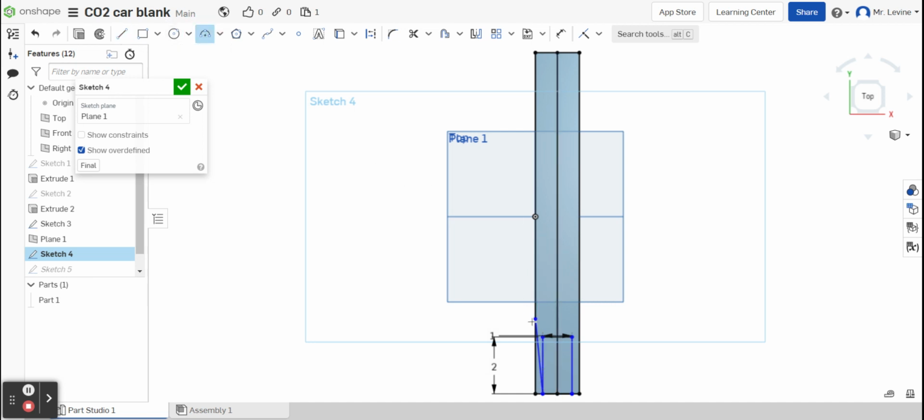So if I want to do an arc, maybe start it here, end it there, and then I'll bend it maybe like that. Don't forget, you are allowed to make it a little shorter. So maybe I leave it like that, and then I am going to go to like a wedge. So I only drew half of it because the top is symmetrical and you really want it to be symmetrical. We don't want to be guessing on symmetry. So I drew one side of it, and then what I'm going to do is I'll use the mirror command.